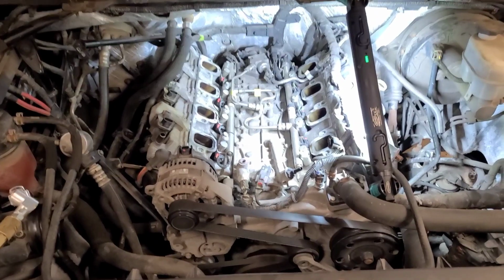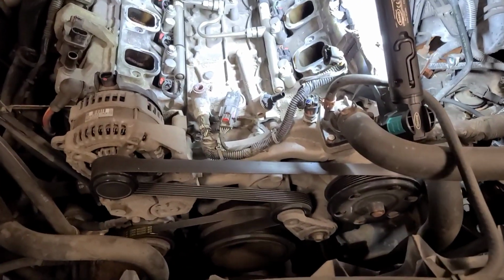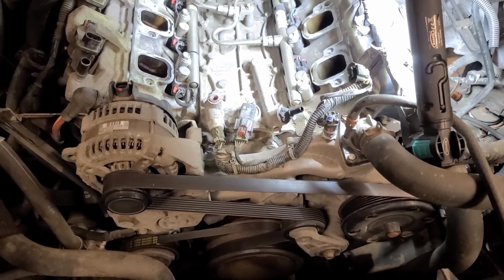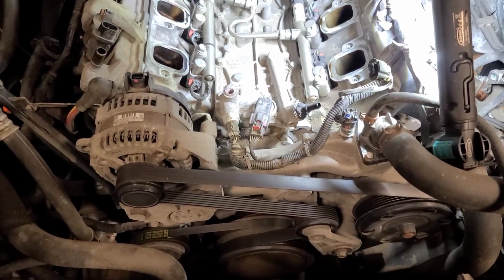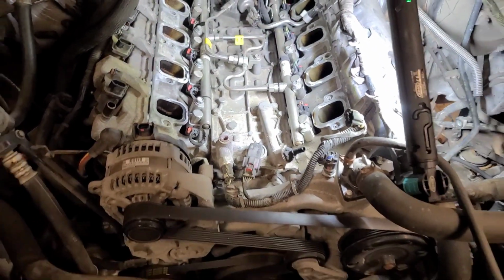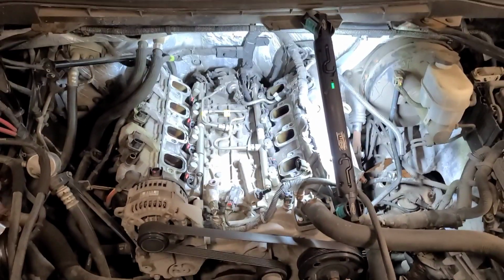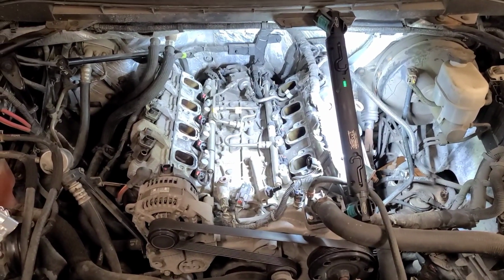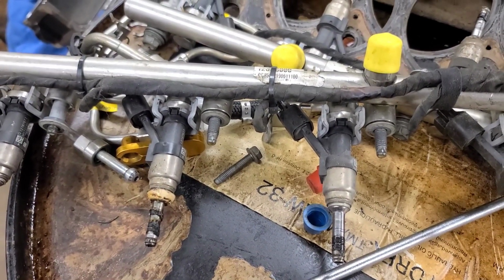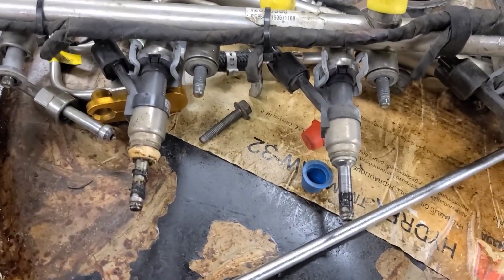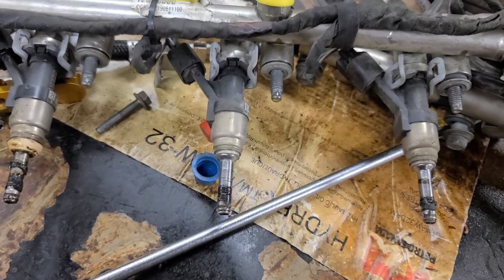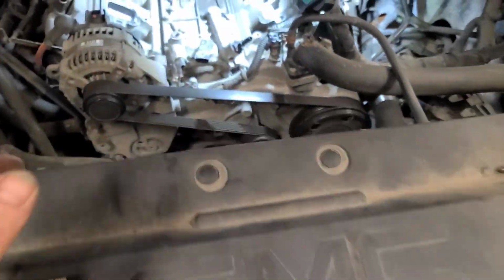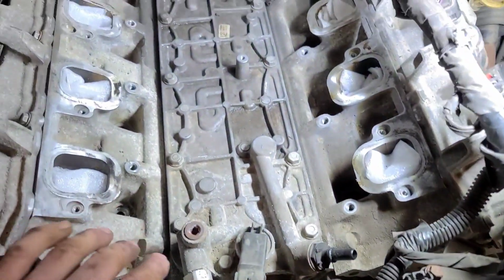So we have the intake off of this thing now. We're going to try and remove the valve lifter oil manifold and free that one lifter using that method that I saw on YouTube. I'll put a link in the description. One of the reasons I even tried doing this was because I know I had these injectors out last summer, last May or June or something like that, and so I remembered the hassle I had getting them out. You have to take the fuel rail out to get the valve lifter oil manifold off.